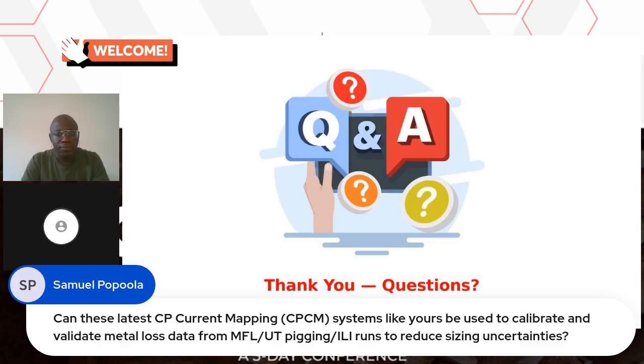The MFL, I think, has a reliability of 80% on accuracy, and UT has 90%. Sizing, so you could use our system to calibrate, particularly when you are talking about external corrosion. For locations where we have higher current demand, which you can know from the system, what external thickness loss are we having in that location? But sizing uncertainties for defects is a little bit imprecise, because depending on the OEM, most times your MFL tool has a 20% error margin, and the UT has a 10% error margin.